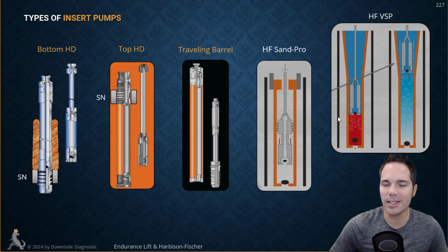The function of this is to compress the gas that comes into the pump. Instead of compressing it on the downstroke, you're using the high pressure of the pump discharge pressure to cycle around the plunger and compress all the gas that got into the pump chamber. So if you can't remediate gas interference by separating it out with a good gas separator, you might look at running one of these style pumps. Of course, there are limitations to this as well. Spacing is very important, and you're pretty much going to need an all steel rod string for this to work.